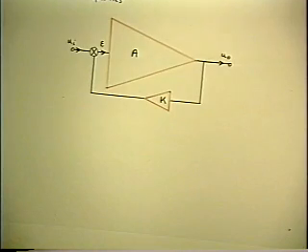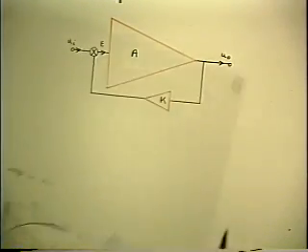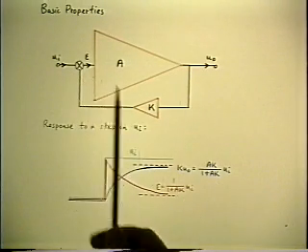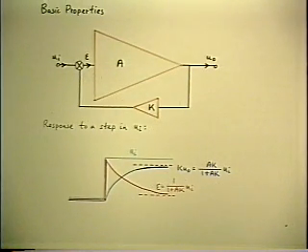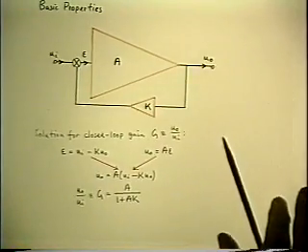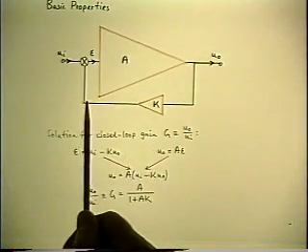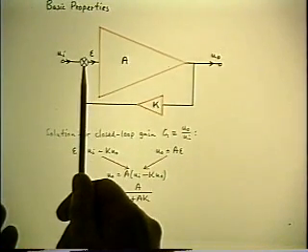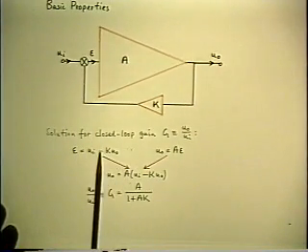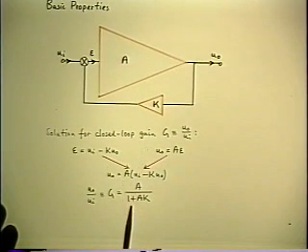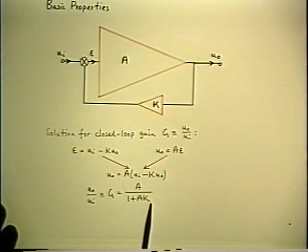Back here in the original picture, I defined these quantities, the error signal in particular, as epsilon is the input signal minus the feedback signal. In other words, I've actually defined this junction as a differencing junction, not a summing junction, by making the minus explicit. So when I follow the algebra through, I get a 1 plus T in the result.